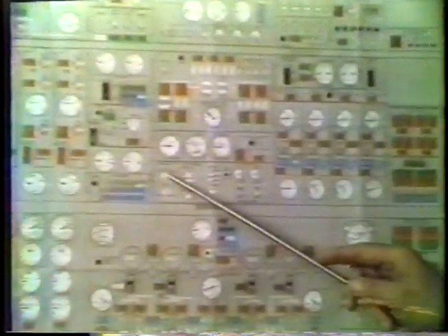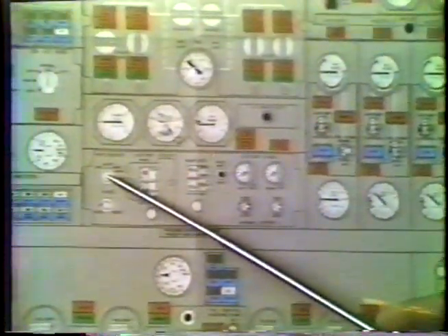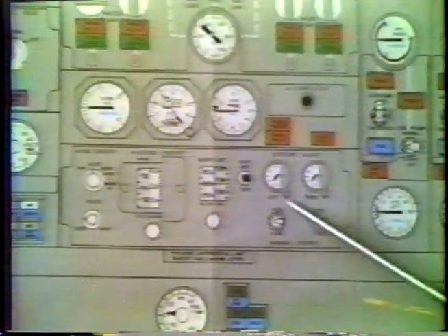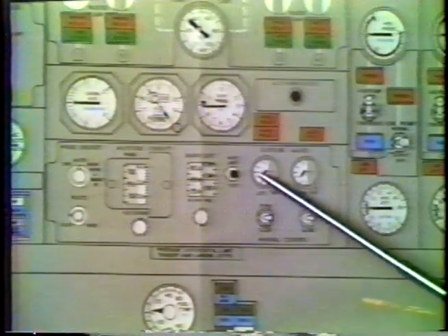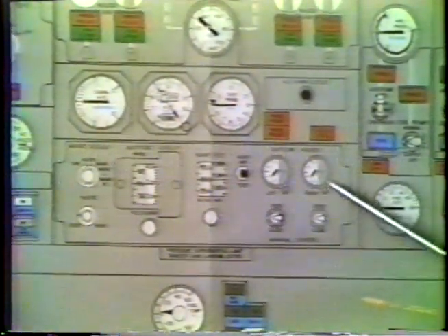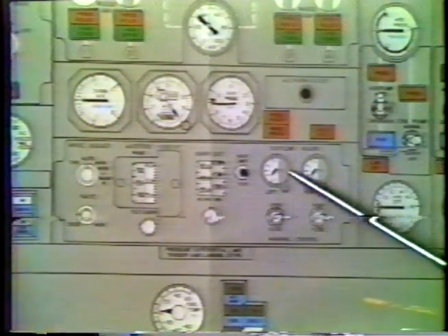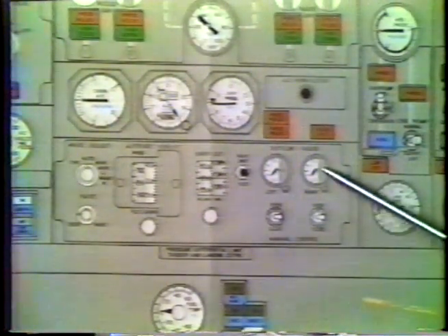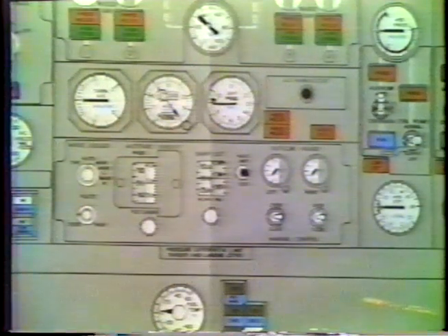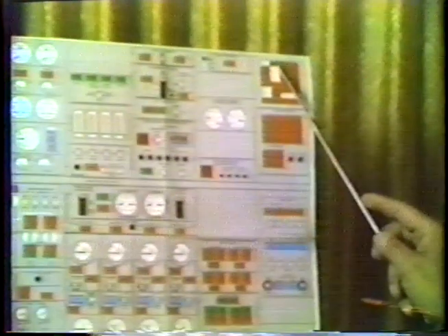The next panel I'd like to talk about is the pressurization control panel. Starting with the mode selector switch in auto. Automatically, the outflow valves are controlled in auto by two separate channels, one for the left outflow valve and one for the right outflow valve. However, in auto, anytime you're on the ground, the outflow valves will be at the wide open position, which is controlled by the ground safety relay green light being on. When the ground safety relay light goes out after takeoff, the outflow valves will do whatever you have set in for the pressure controller.